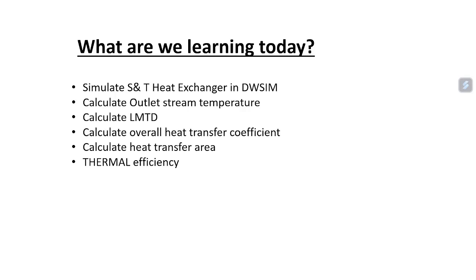So moving ahead, what we are going to learn in this. So definitely we are going to simulate a shell and tube heat exchanger in DWSIM, and calculate outlet stream temperatures, LMTD, overall heat transfer coefficient, heat transfer area and thermal efficiency.